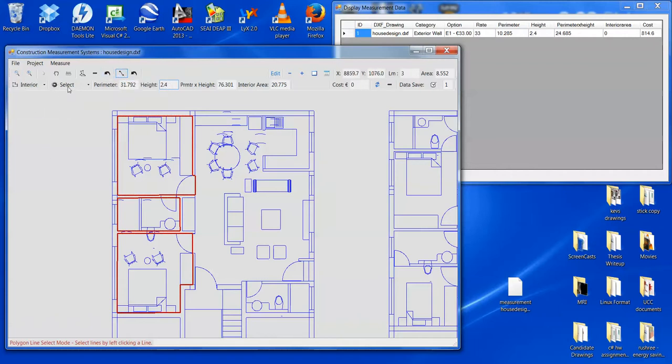So the interior walls, let's choose an option. We have different options for the interior walls. They populate according to what category we've chosen. Again, I'll go for the most expensive, which is I6, which is screw fixed 2 number 12.5mm fire resistant plasterboards to existing timber stud partitions, tape joint and skim finish. Okay, so that's another good option.